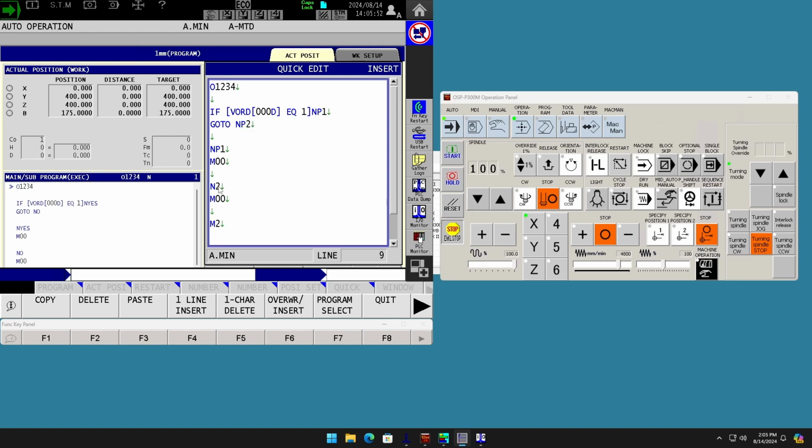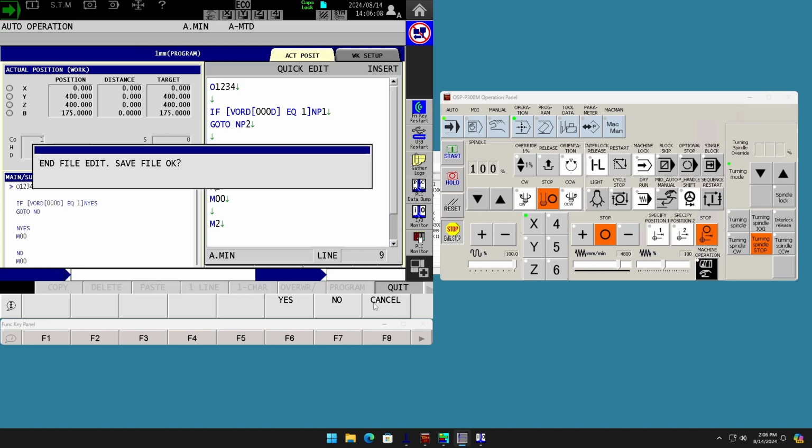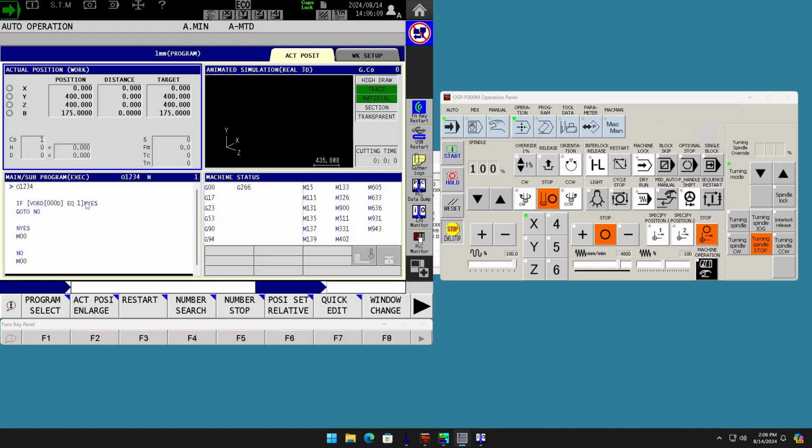They're not going to say, hey, go to N5 and then somehow magically jump into my program that they weren't even supposed to be in, running something they weren't supposed to do. So if you see anything that starts with the letter N, at least as far as I can think of, there's no system word that starts with the letter N. It's always going to be N, and whatever follows that, letters or numbers, it's just a value, a label that the Okuma is going to search for.